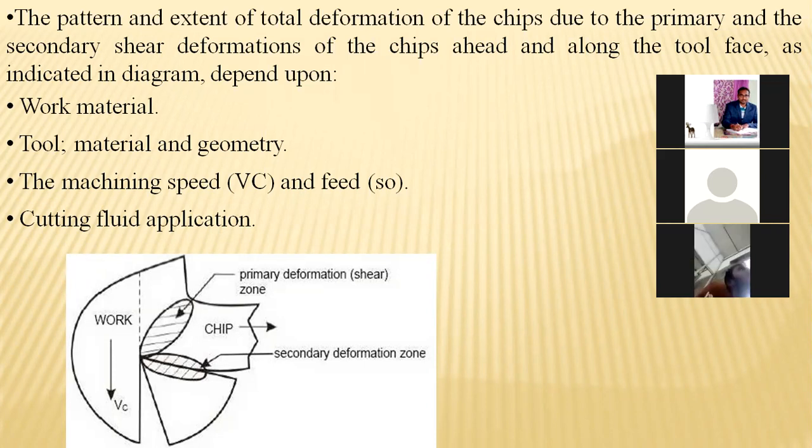The best example is that in the case of a drilling machine, 4 mm, 6 mm, 7 mm different diameter bits will be used for its working requirements. So if the dimensions deviate, the nuts and bolts for the fixation or assembly will not match perfectly, and some other alternative needs to be commenced, which will deviate the fixation concepts. And even the machining speed and feed ratios are to be examined.